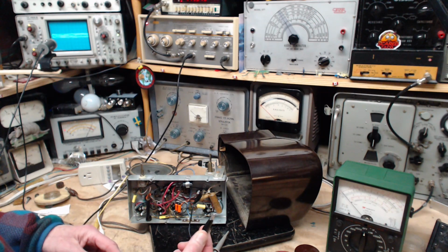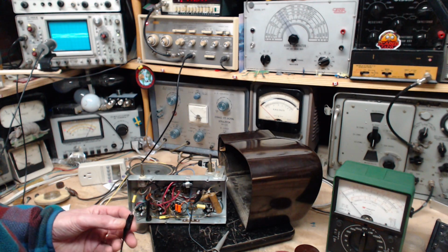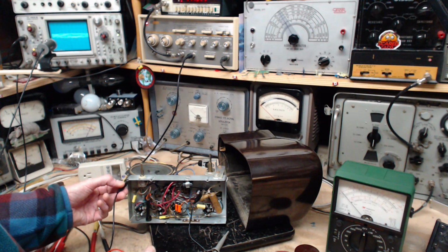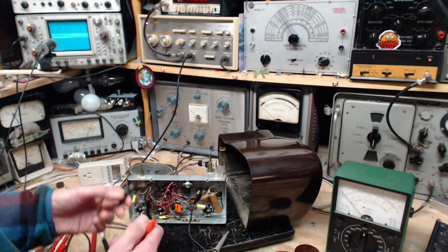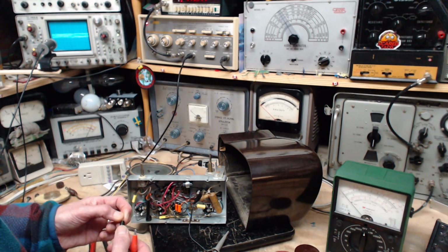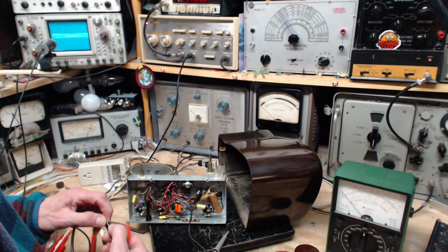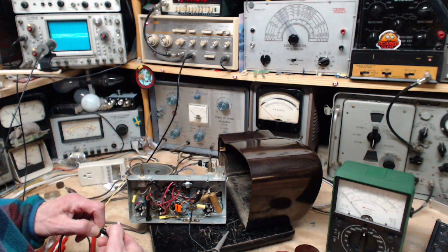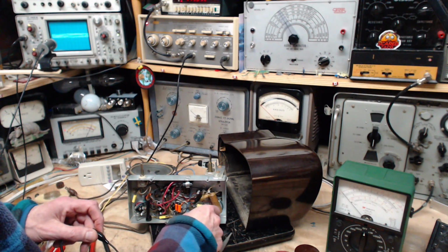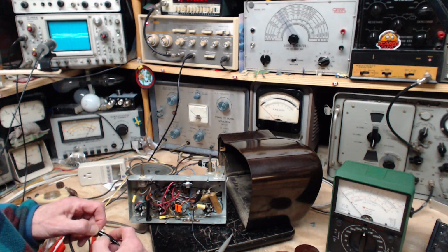And now I got another ground connection. And I can't put this ground connection anywhere different than this one. So I'd have to ground it on the chassis. Oh, that's not going to work out well. That wouldn't work out well. I have to ground it, but I can't put it on the B minus and the chassis at the same time. That's definitely going to completely disrupt the operation of this. I'll basically have to put a short circuit across it.